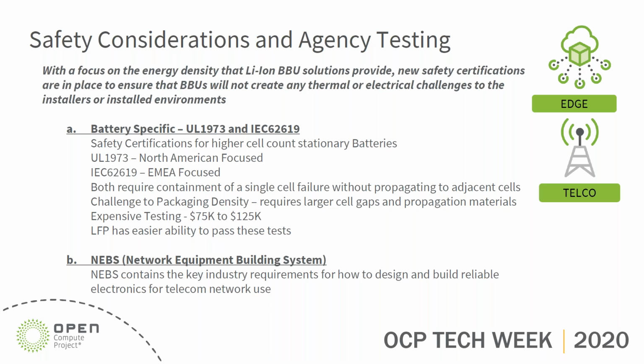And what we've seen is that even some of the existing vendors who are doing battery backups for radio towers today have had to come out with new product lines just to be able to support meeting these certifications. And just the scoop on the internals, and I'll show you a picture of that in a minute, means that you have to add gaps between the cells, and you may have to add material in between the cells to achieve this certification. So you have to redesign your pack to meet these certifications. And then of course NEBS, which has a very long history in safe and reliable electronics.